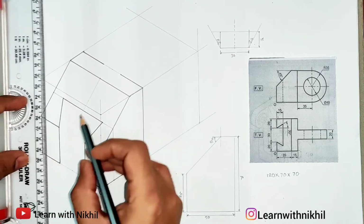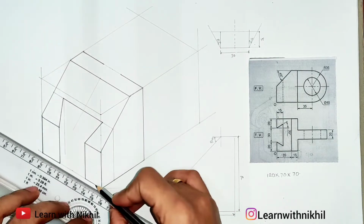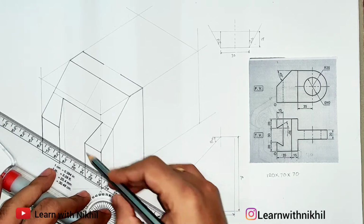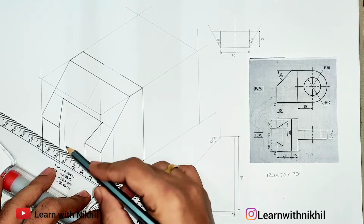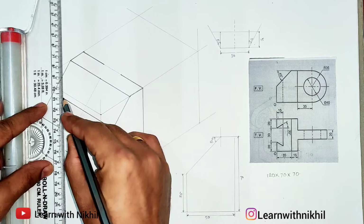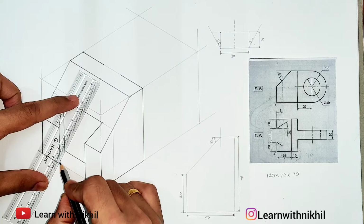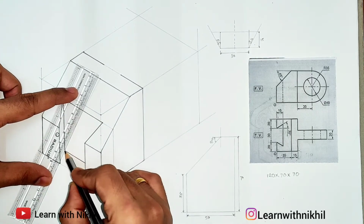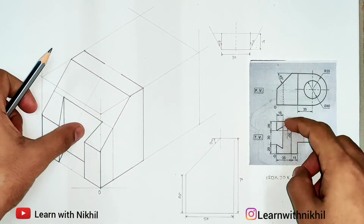So taking this as the reference line, drawing it here, the light line, until where it is cut inside, it is around 15 millimeter. So 15 millimeter from here, the reference line, this is the cut depth, drawing it dark. Now joining this and joining this. So this is how it is cut. You can take this as a reference line and join this. So this part is done, the front part.